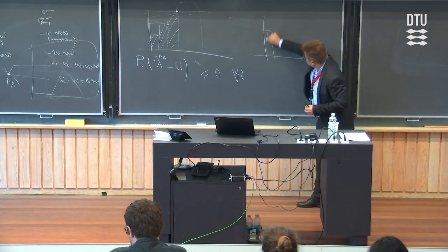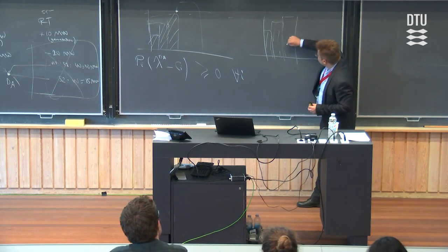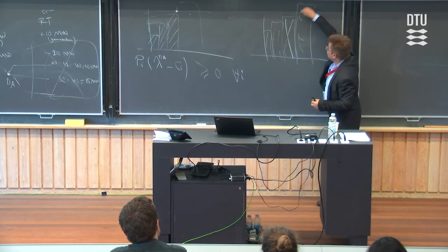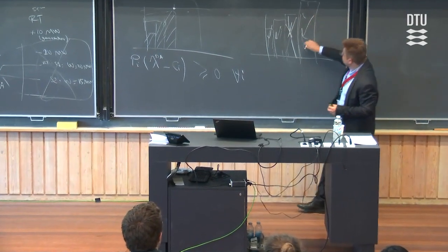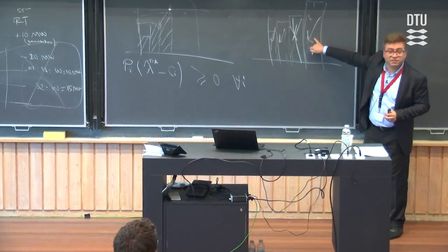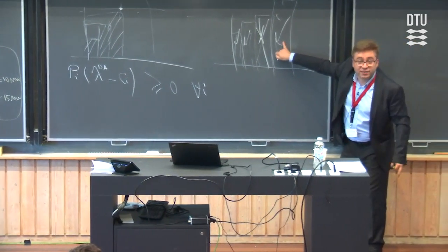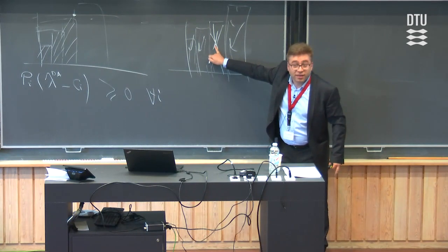Maybe you will see that this is dispatched. This is dispatched. This guy is not dispatched. But this generator is dispatched. So this is dispatched, this is dispatched, this is not dispatched, this is dispatched. Why? Because this guy will provide flexibility, upregulation in the real time. So we need it in day ahead to have it. So though this is cheapest, it's not dispatched in day ahead.